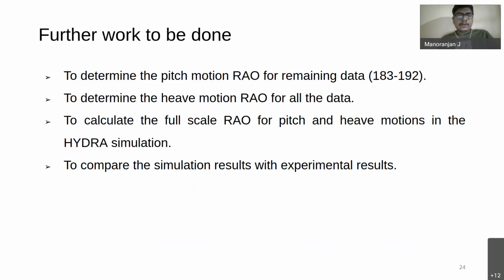And so what is the remaining work? We have to determine the pitch RAO for the data corresponding to the improper cases that we are observing. We are still working on that. Once the pitch RAO is done, we will move on to the calculation of the Heave RAO, which is more challenging. The next aspect is to calculate the full scale RAO for the pitch and heave motion in the Hydra simulation, and compare it with what we have obtained experimentally.